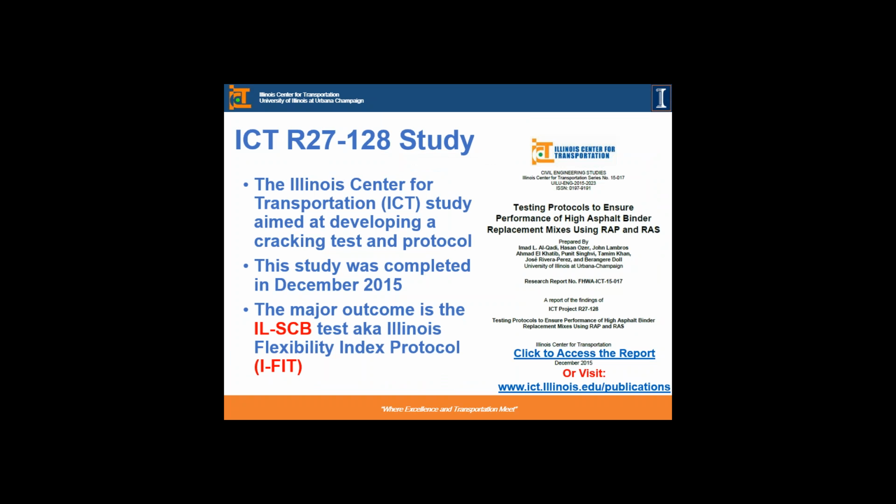And this is basically this project. This paper presents partial findings of the recently completed ICT project R27-128, and the report was published by the end of 2015. And the major outcome of this study was this Illinois SCB test, as we initially called it, also known as the Illinois Flexibility Index Testing Protocol, I-FIT.